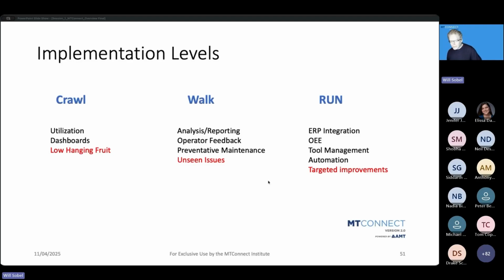That's when you start combining things like sensor data. I take my sensor data, I combine it with my usage data. Now I know that even if it's being used, let's say I'm seeing temperature warnings coming up on my spindle, I probably want to do more aggressive maintenance on that. Or if I see vibration, or the machine isn't holding tolerance as it should be, all of these things will be signals back into a preventative maintenance scheme.